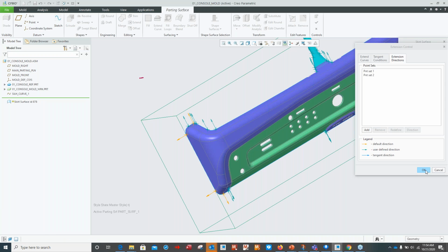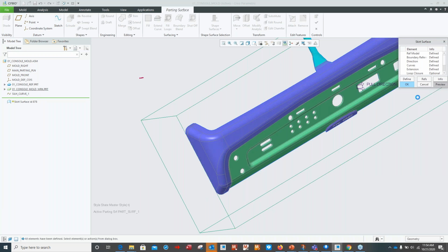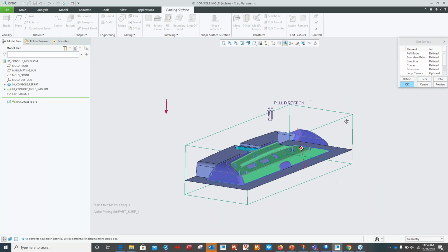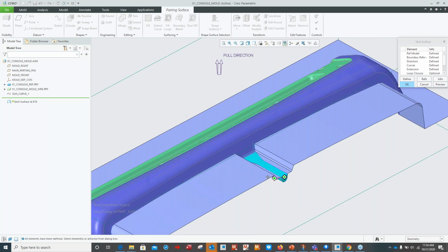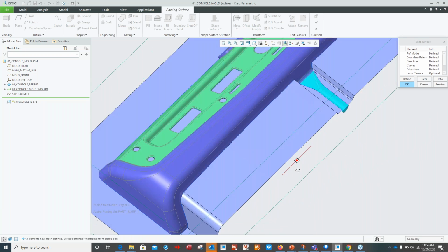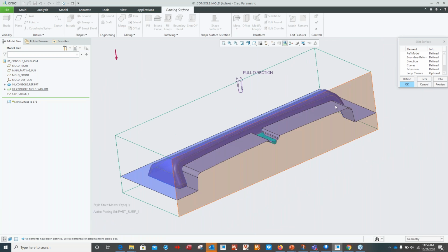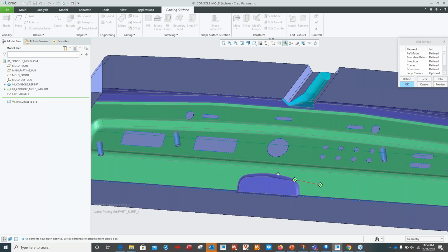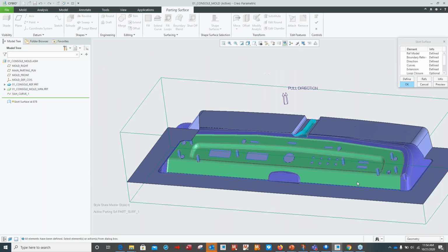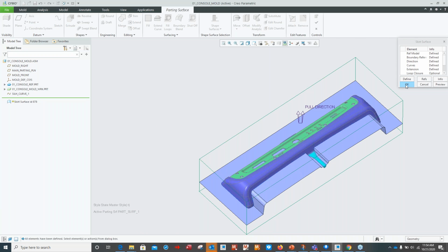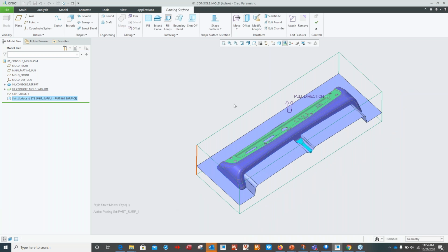Okay. And we select the preview. And as you can see, at least our parting surface shutoff has been developed for the core and cavity split. It's closed up all the loop shutoffs for all of the hole features that we have here. And as simple as selecting OK.